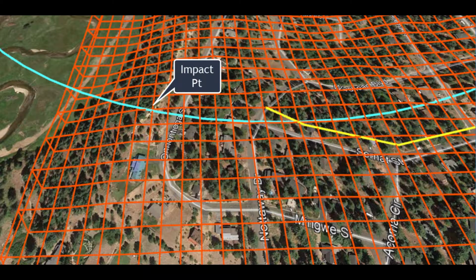This slide depicts a flight path from the left, as depicted in magenta. You can see that the flight path starts out above the 85-foot obstacle mesh and then flies under it at the depicted impact point. This does not guarantee this as an impact point, just that it can no longer fly above 85-foot obstacles in that area.